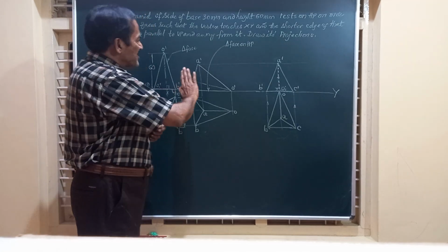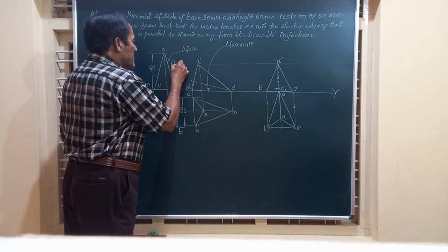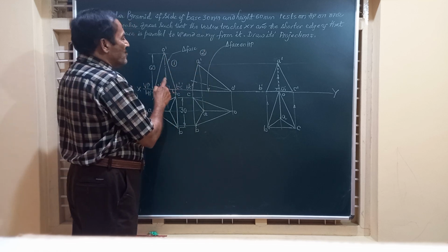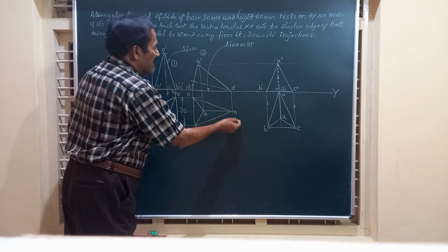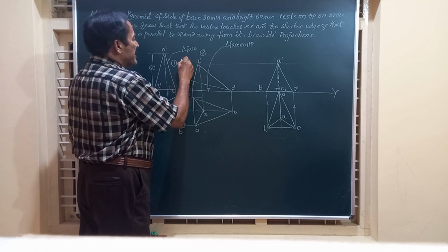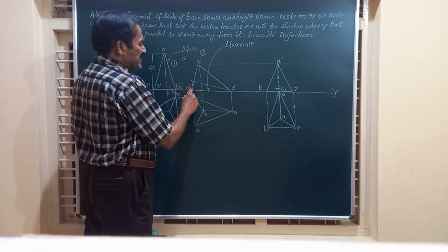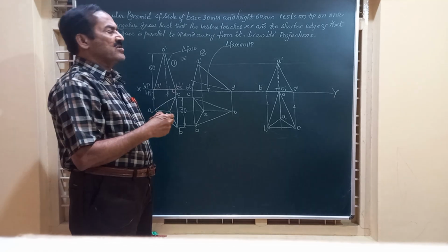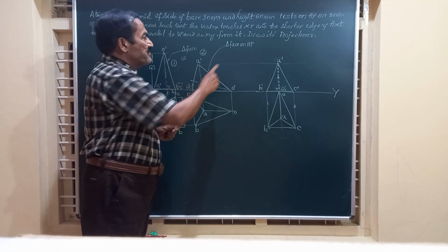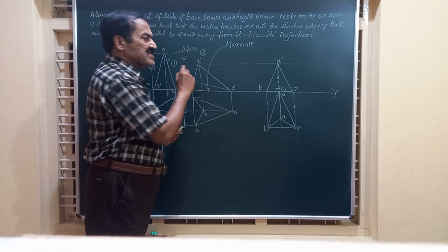Since the pyramid has to rest on this triangular face on HP, I am going to draw this figure 1 as figure number 2 such that this triangular face O dash, B dash, C dash is on HP. So I have drawn this figure here, and you find these two figures are exactly identical. And we mark this as A dash, B dash, C dash, and in the front view of the second position, O dash, B dash, C dash represents a triangular face because there are 3 points O, B and C.